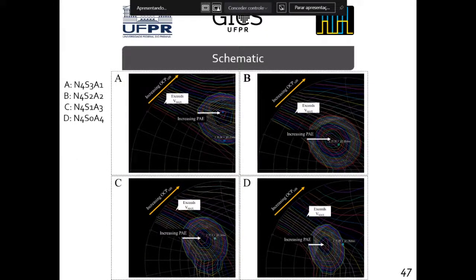The four insets show that the selected load pull impedance is an adequate choice for all four modes at 2.4 GHz. The efficiency increases as the radius of the closed curves decreases. The linearity increases clockwise. Although this load pull simulation shows the capacity of such circuit achieving higher linearity values, one should carefully consider which load impedance to select, because some impedances cause one or more transistors in the power core to exceed Vmax.